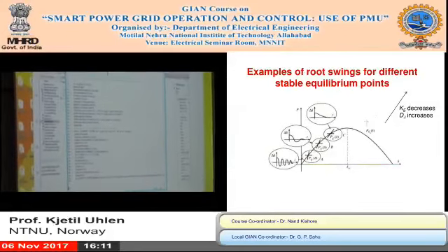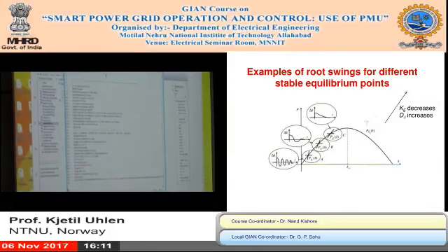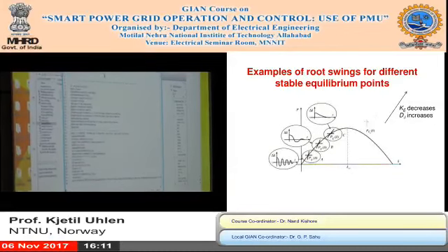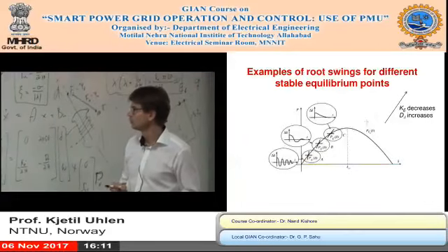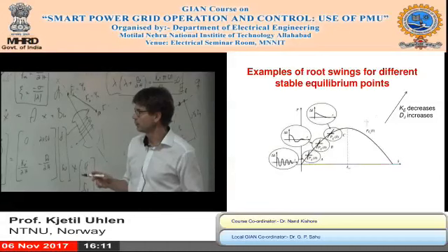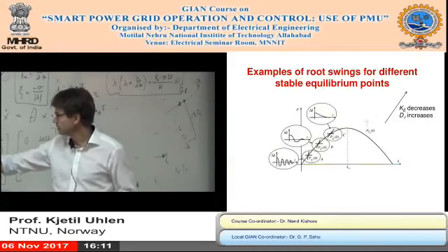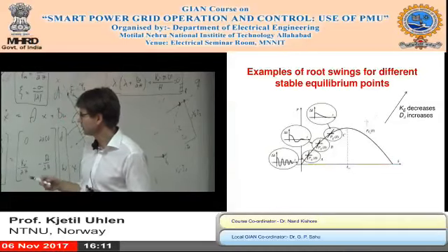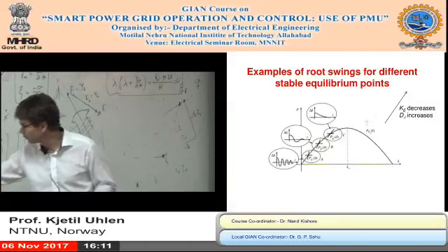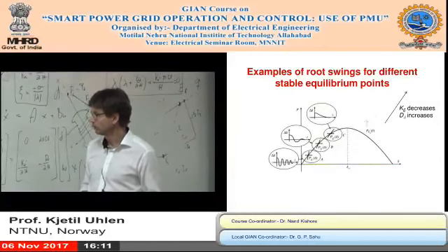What it does is I define the operating point in terms of power and reactive power that's supplied to the grid, the infinite bus voltage, and I define the necessary parameters like xd, xq, xd dash, xq double dash, xd double dash, if I want to include the formula for the damper windings.